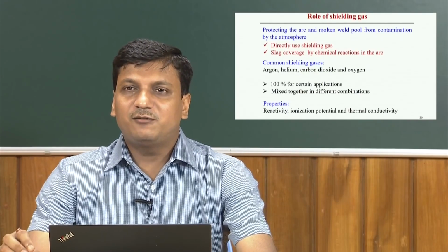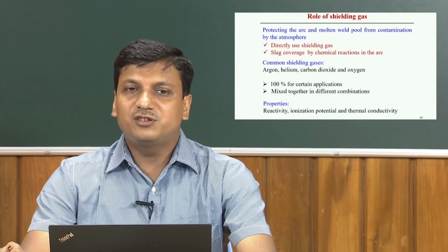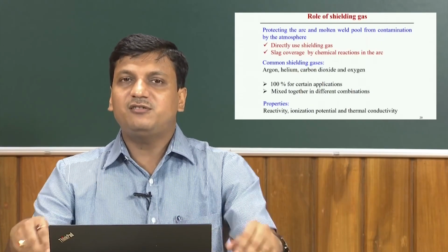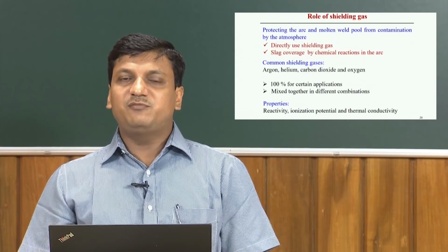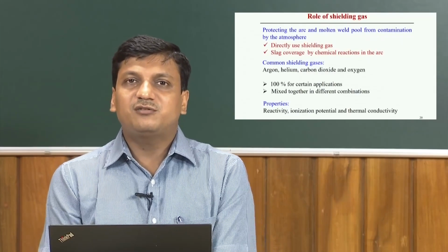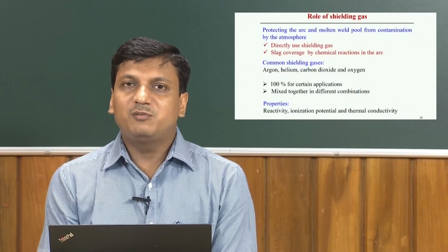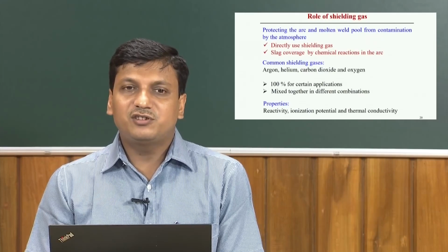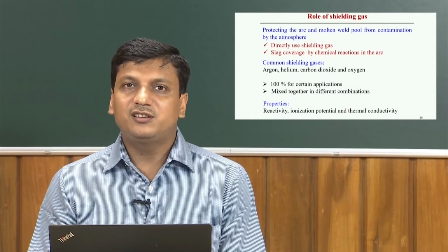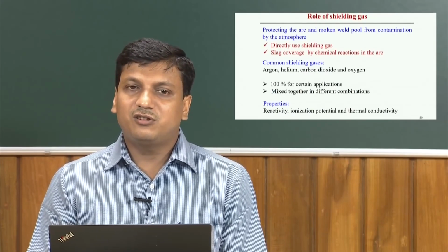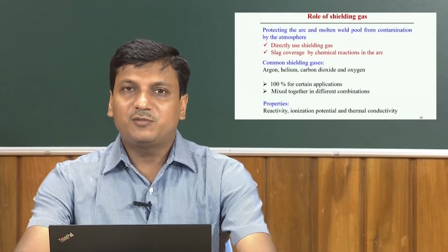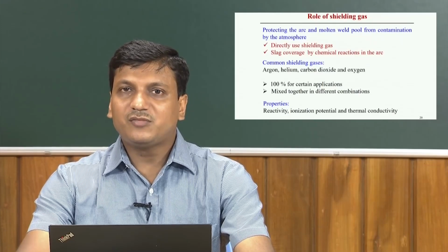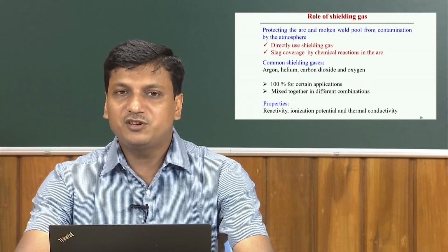But the basic principle of the shielding gas relates to reactivity. The shielding gas can be decided based on its reactivity with the molten pool in that high temperature environment, and its ionization potential, that means how easily it can be ionized or not, and the thermal conductivity of this type of gas or of the workpiece materials.